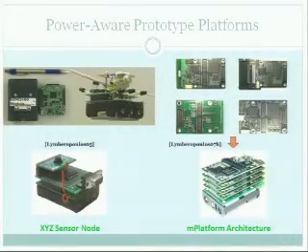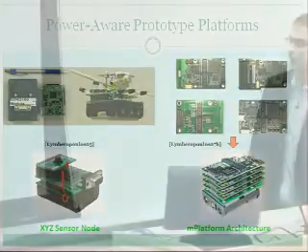Now, these different design trade-offs, bottlenecks, and techniques that I'm going to be describing, I'm going to describe them in the context of the two sensor nodes I've actually built. The XYZ sensor node at Yale University. This is a single processor platform, but it goes from the simple 8-bit microprocessors up to the case where we use a 32-bit ARM7 TDMI-based processor that can operate from 2 megahertz up to 60 megahertz. Now, the key novelty in here is that we can combine this processing power with extremely low power sleep modes that a very low-end microprocessor can actually have.